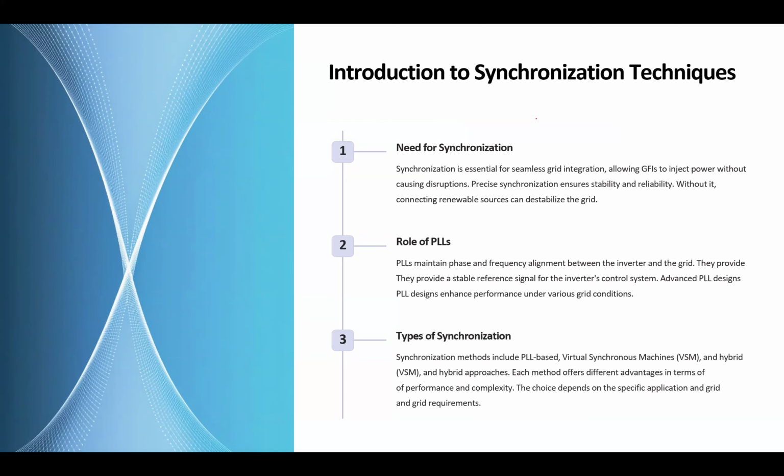We have to get synchronized to the grid because our grid-following inverters are not capable of creating a frequency and keeping it at that level. So they have to follow the grid for that. They have to rely on the grid for that. Because of that disability of the grid-following inverters, we need to synchronize.